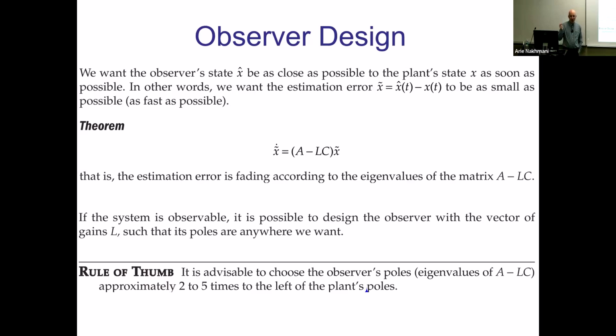In physics, y will have some tolerance, which means you will not know the actual y. You will know y plus minus some tolerance plus noise, right? This is what you will actually have. So if you build your state estimator based on incorrect y, and you do that just based on a few points from y, it will converge to wrong values of x for natural reasons. So the estimator will be wrong all the time.